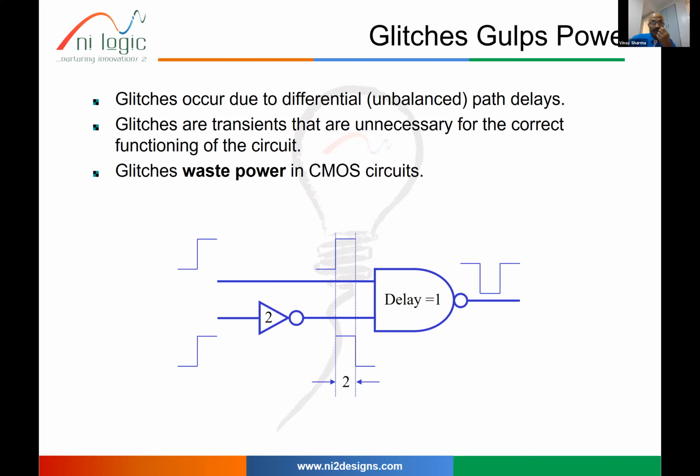Now let's look at how the power consumption goes up. The power is computed by this formula, which we have already shared. It's P equals F C V squared. So it's the frequency, capacitance, and the voltage. V is the voltage on which the transistors are working. C, the capacitance, represents the number of transistors in your design.